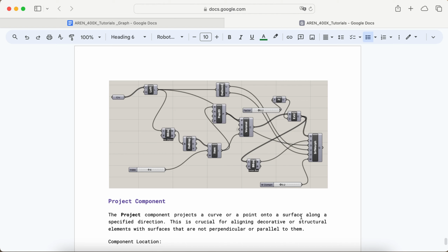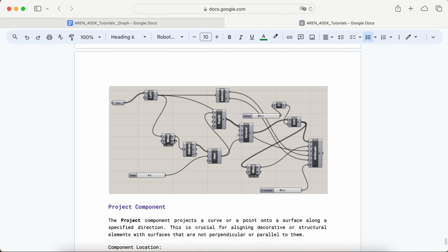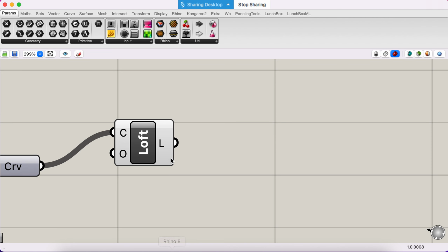Okay, so we have the loft surfaces. Let's create a bounding box around it first. After we create the bounding box, we get one of the items, which is the surface of it, which gives us the area for this surface itself. And then from there, we have a flat surface. We put populated 2D points on it, and then we create our Voronoi patterns. And then after we have that, we morph it back to the surface itself. So let's just start going back to Grasshopper.